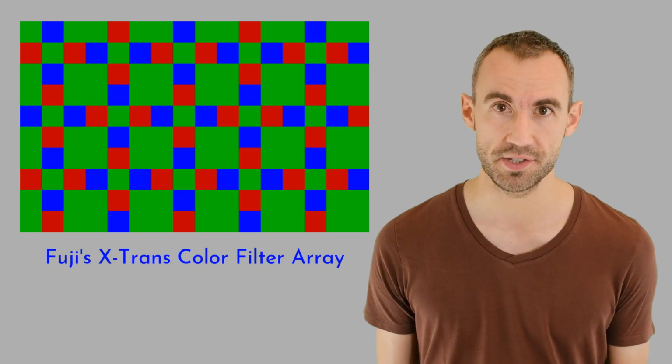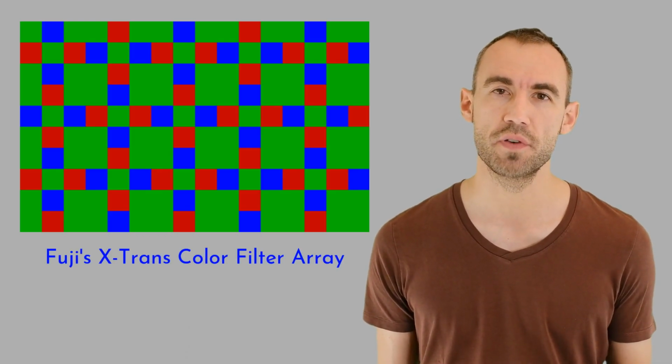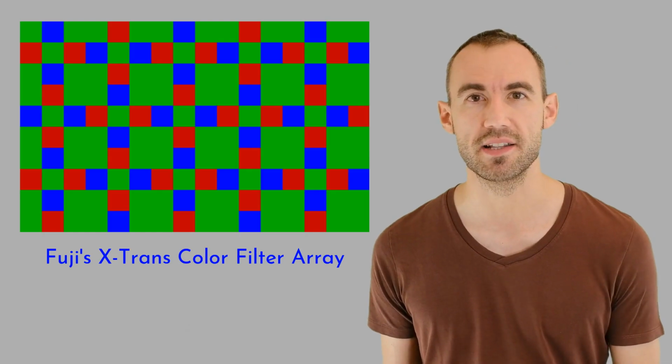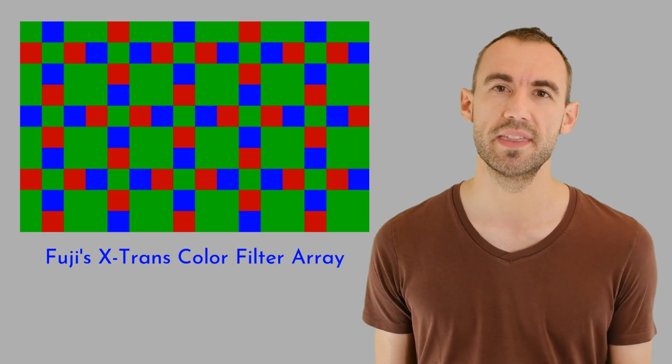We'll skip the demosaicing process for today because it's too much to talk about here. But in short, there's a color filter array on top of our sensor, so we only get one color at each photo site. But for a photo, we need all three colors at each site, and we get those with the demosaicing process. I've actually implemented two demosaicing methods once. One was a simple linear interpolation, and the other was the variable gradients method. And if you remember correctly, then they shouldn't be affected or affect the vignetting correction either, which would make sense, right? We're just interpolating. We're not actually changing the value of any pixels.